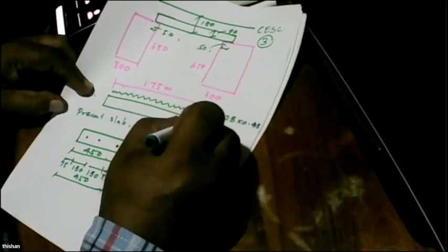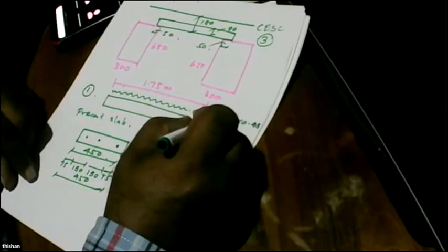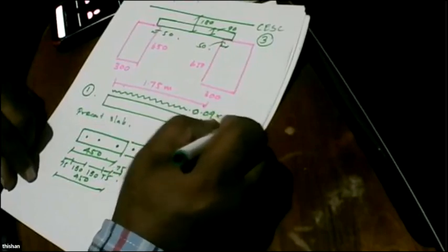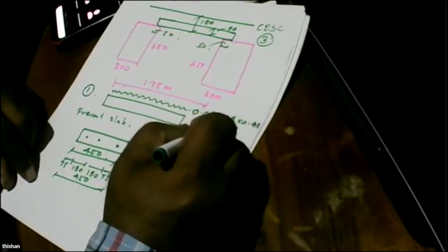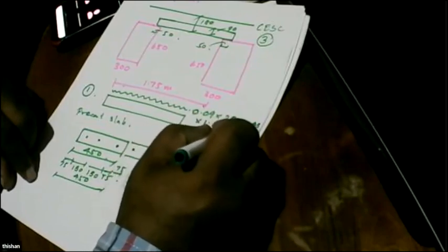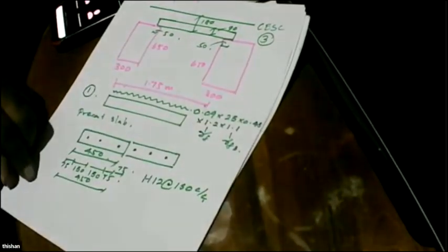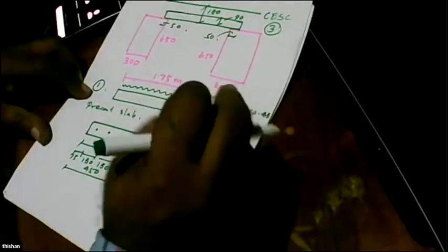This is the load, and you have to multiply that load by 1.2 multiplied by 1.1. These are the factors of safety, gamma F, and this is called gamma F3. So there are two factors of safety, and I'm just talking about the BS loads.